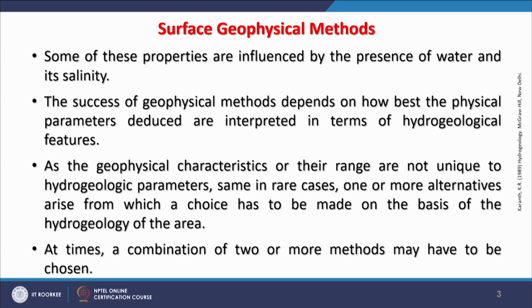So, sometimes we first start with the resistivity method, and if we are still not yielding good results, but the requirement of water is there or exploration is very much required, then we may go for another method. So, a combination of 1 or 2 or 3 methods of geophysical surveys can be adopted for one single area, and this happens only in those areas where there is a problem of getting water. Areas like the Indo-Gangetic plain have water at certain depth, which of course varies from area to area, but still we know that water will be available. But there are areas where water is a big problem, where we might go for 1 or 2 or 3 methods for groundwater exploration.